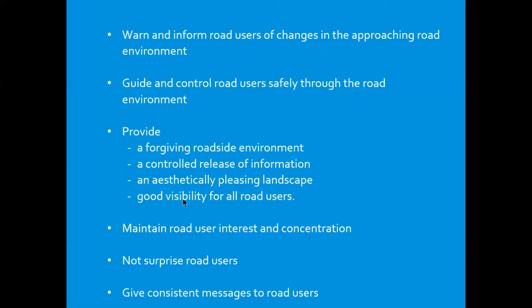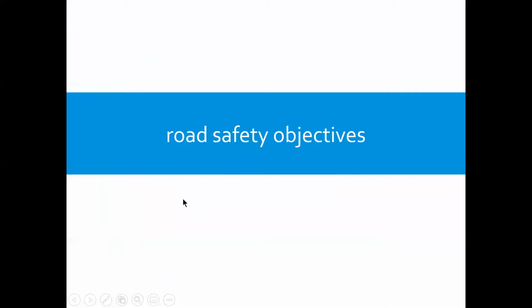So what are the safety objectives? Broadly, there are three avenues of action possible for mitigating road crashes and their consequences: by reducing the possibility that runoff will occur; once the runoff does occur, by providing opportunities for the driver of the vehicle to recover and return to the road without incident; and if a crash does occur, by providing design elements to reduce the severity of that collision.